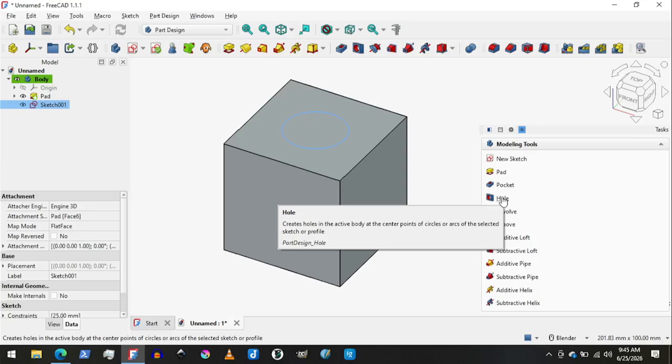So I'm going to show you a better way to do it that would recalculate the hole in the cube. I'm going to select another face and create a sketch. Now the problem is, this time I can't just cheat and link that hole to the origin. I have to come up with a different way to lock it to my face. So I'm going to press the G key and the X key, and what that does is it brings in the edges of the shape I click on and uses them in this drawing.